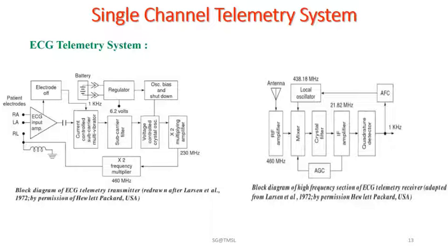It needs the mixer, which uses the square law characteristics of FET to avoid interference problems due to third order intermodulation. A crystal filter is there. It is an 8-pole filter with 10 kilohertz bandwidth, which determines the receiver selectivity.